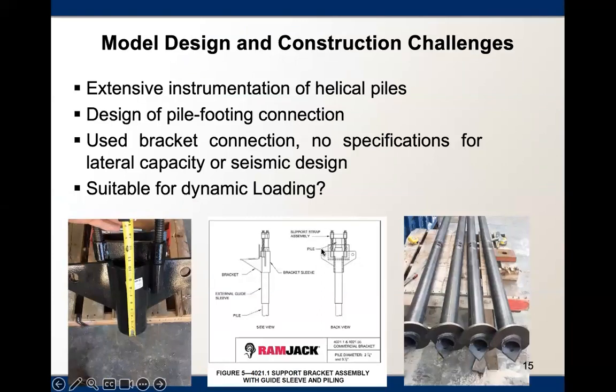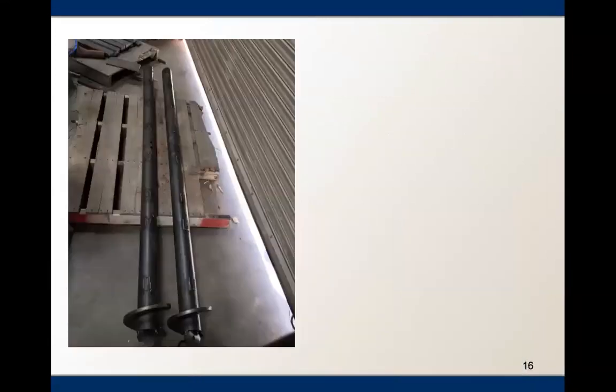All the helical piles were extensively instrumented using strain gauges. It was a very tedious, elaborate work to do it right, to avoid any damage or loss of data as a part of the test. We use a bracket connection to connect the piles to the foundation. And that was another challenge, because the design did not include it for seismic design. So we had to make some assumptions and do some in-house design for that. And I think the big question was how suitable for dynamic loading it was going to be. And I think at the end of the testing, we were able to answer that question.